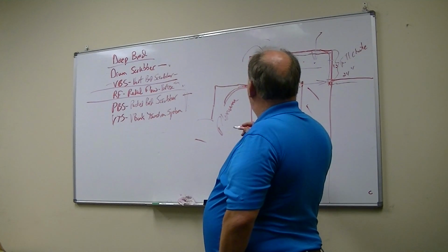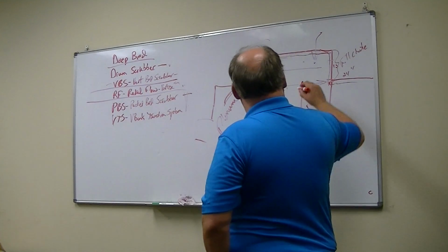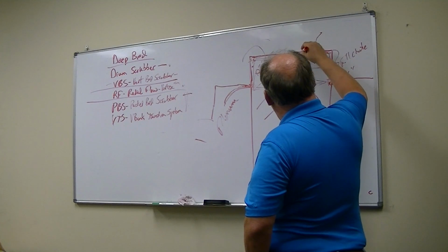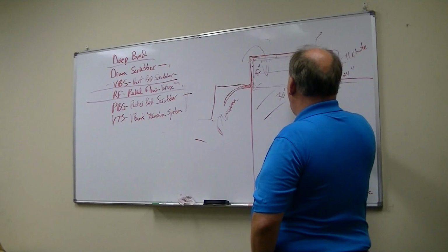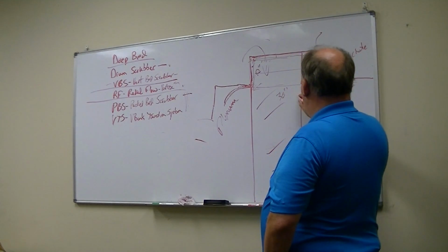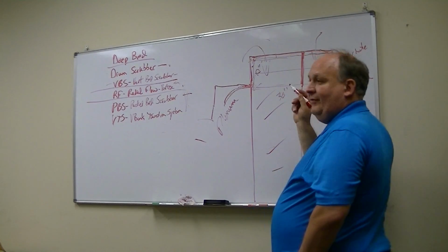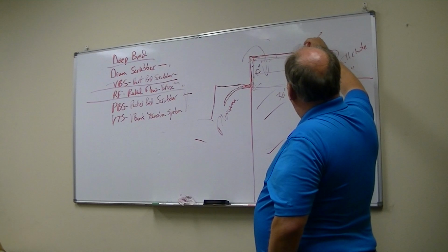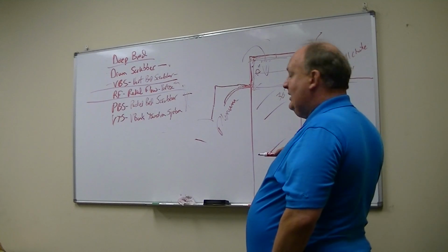Okay, but the way that you make sure that 12 inches is enough is that you make sure that this wall here above this screen, so keep in mind this is going to be a porous screen here that air flows through, but you make this a solid wall. So this is a baffle, we call it, okay? And you make sure that this goes all the way to the top and that this lid comes in contact with that, and that you put some gasket there to make sure it completely seals, right?